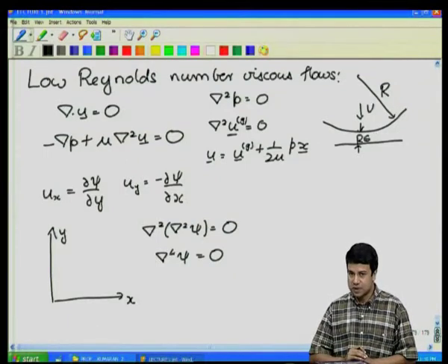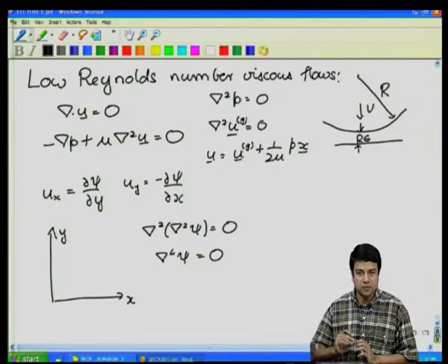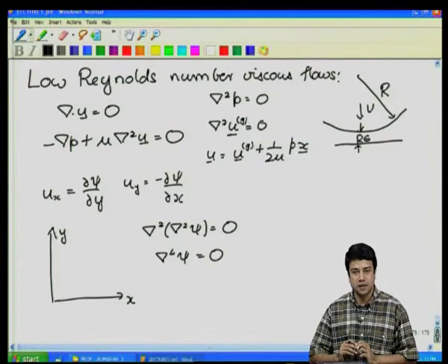And in this case, we used scaling principles because this is a nearly unidirectional flow. The distance between the surfaces is small compared to the lateral extent, and therefore, the flow is nearly unidirectional. At any point, if you do the scaling analysis, you will find that the velocity profile is close to a parabolic profile, and using that one can find out what is the pressure difference between the center of this gap and the ambient pressure, and that difference basically drives the flow.